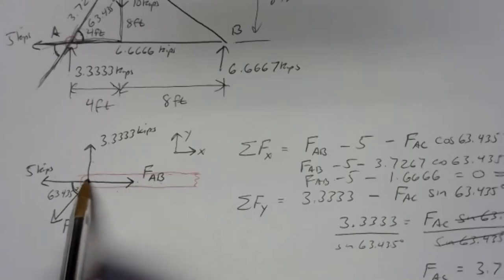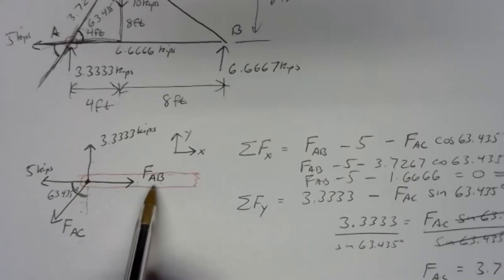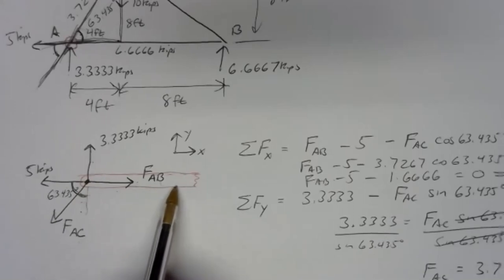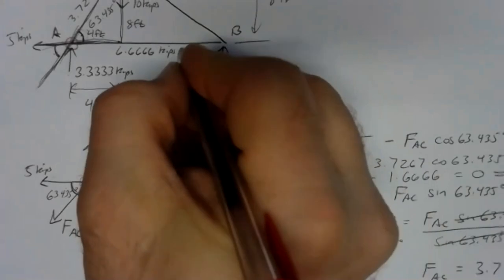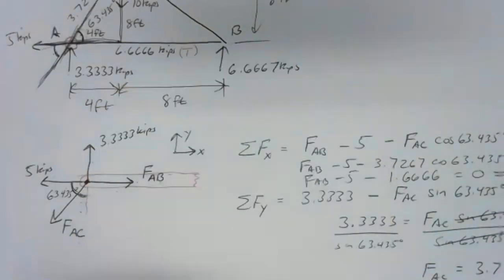So the member is pulling the joint in toward the middle of the beam. Only things that are stretched out could do that. This is tension. So member AB is in tension. And so I'm going to put a little parentheses right next to that that says T.